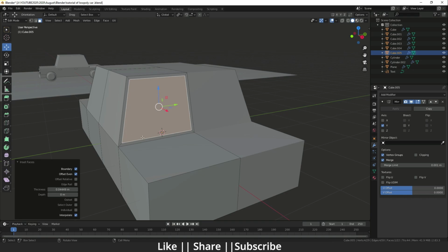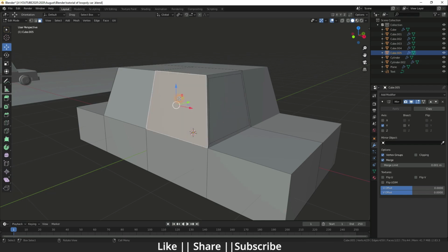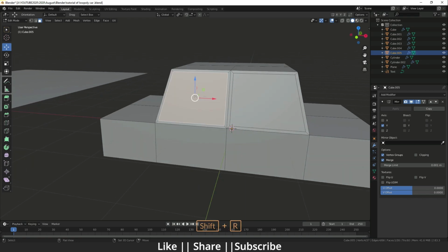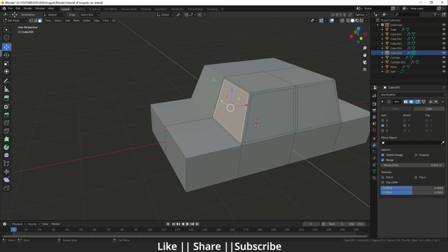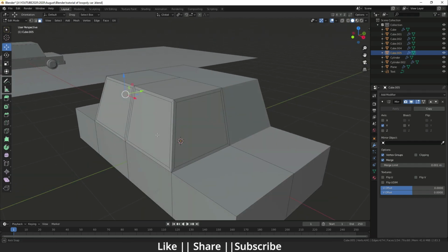Okay, and now I'm going to use this shortcut command. It's Shift R. So I will select that face and press Shift R, so that the same value of insert is used here. Then I will press Shift R again, then Shift R again. So here you can see we have a perfect line here and the same value of insert.